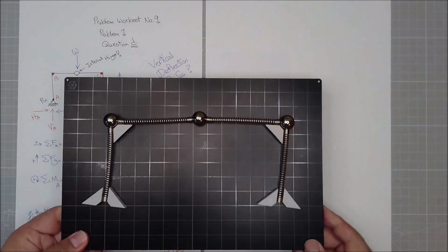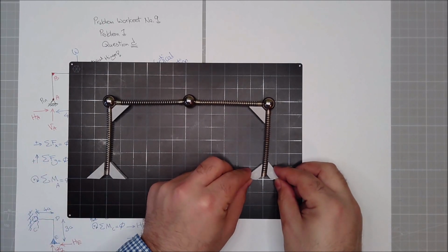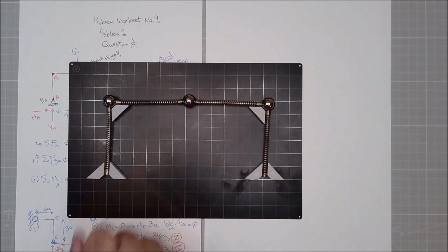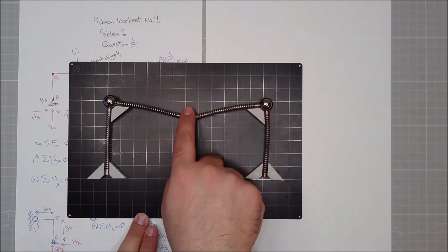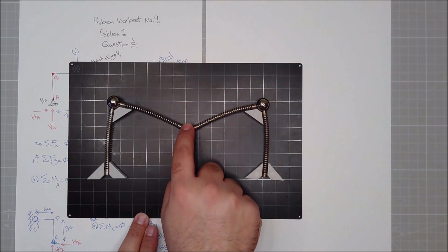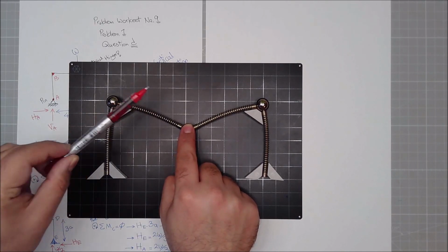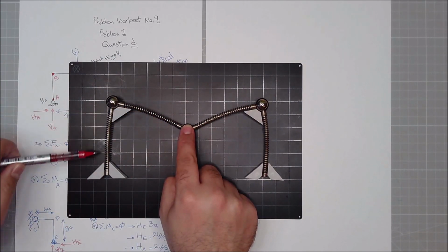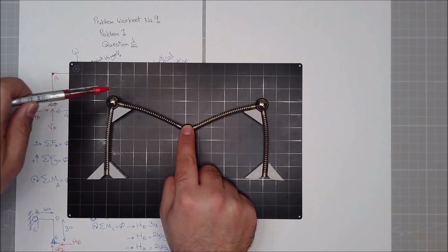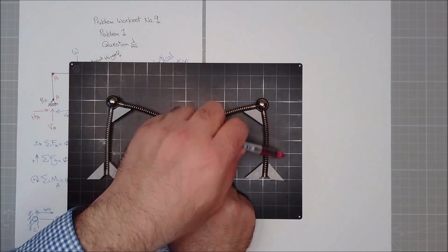So this time, my frame is actually exactly like what we had before. Symmetric, a point load is applied. So this comes downward. As you can see, where are the tensions? Tension, tension, tension, tension. So I'll have to draw the moment diagram for outside of the column, outside of the beam, outside of the beam, and outside of this column.